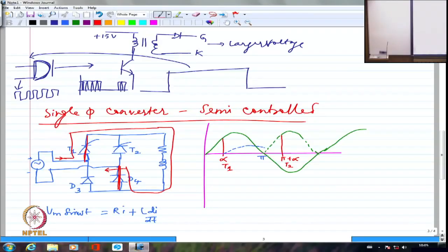So if this is a short circuit and this is reversing its voltage, because omega t is pi already, I will have plus here and minus here when I'm talking about the negative half cycle. This plus is connected through D4 to D3 here. This minus is connected here.